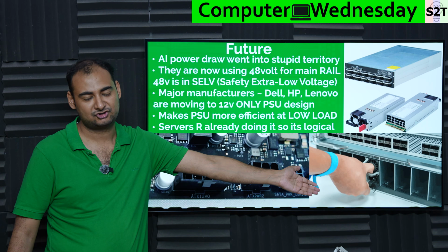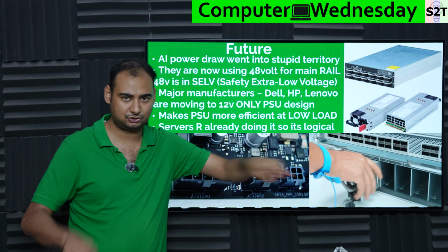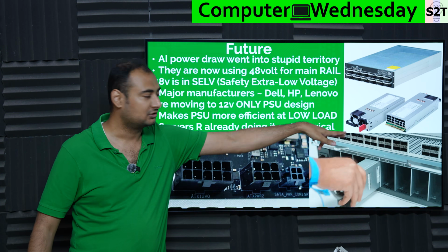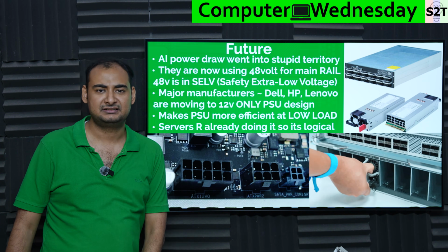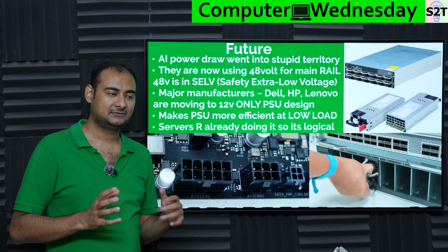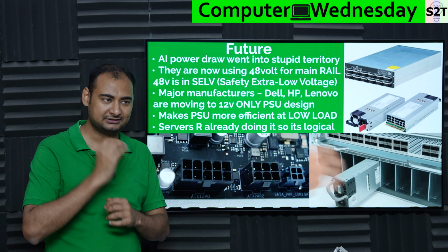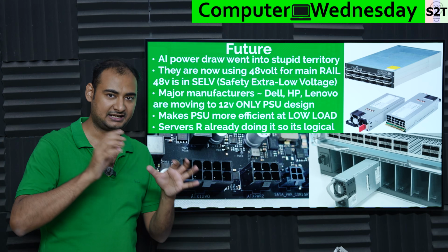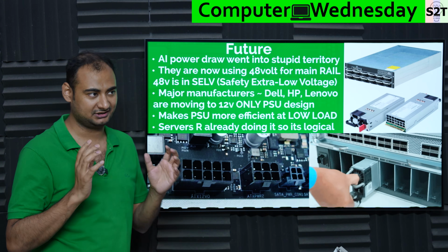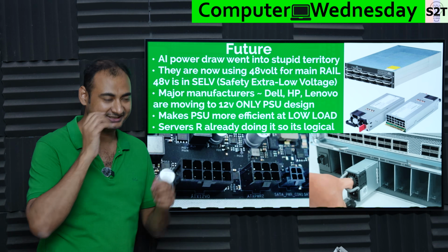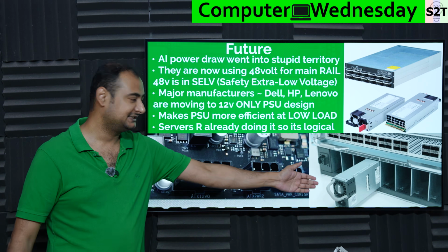That's why servers have hot swappable system. They're like, okay, but they have like 2 spade connectors, like big puppies. Those are 12 volts, but they have a lot of tiny pins. What are those? Well, there's a sense, handshake, and those are in those natures. It's not what you call 5 volt or things. It could have that, but again, those will be just for sensing, just for handshake. It's like, you know, how your USB-C connector has a CC pin for handshaking. So it does not directly give 48 volt to your mobile phone and booms it. So that's why these things are hot swappable.